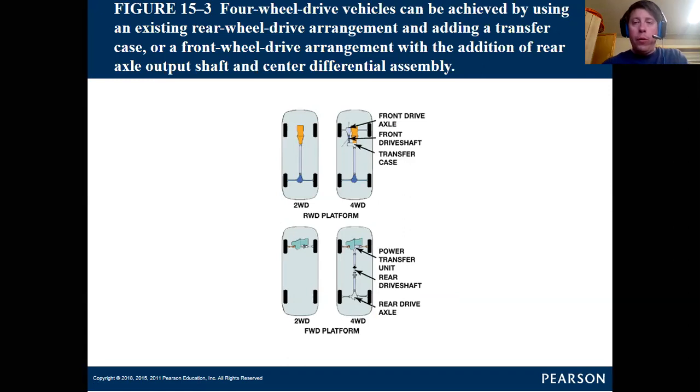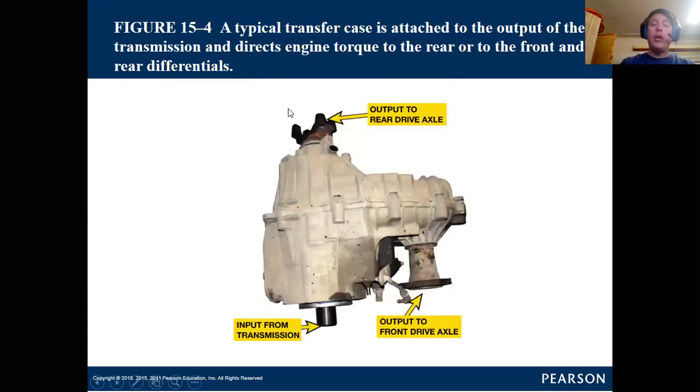You have to think about the componentry here for a second. Transfer cases simply engage the rear drive shaft and the front drive shaft to achieve four-wheel drive. When they're in two-wheel drive, only the output to the rear shaft is engaged. The output to the front drive shaft is disengaged. So if it was disengaged internally in the transfer case, but still mechanically linked to the front wheels, that front drive shaft would spin 100% of the time.